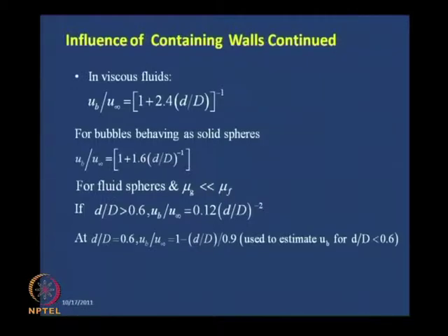So, this is how we use the drift flux model for the bubbly flow pattern. Now, remember, whenever we are using the drift flux model for the bubbly flow pattern, usually the acceleration pressure drop and the frictional pressure gradient are much less as compared to the gravitational pressure drop, particularly in a vertical pipe.